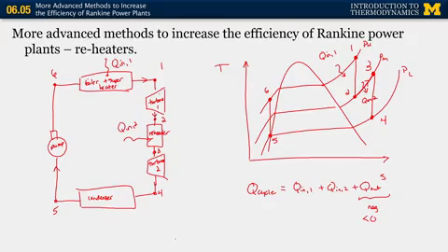Now, I drew this as a system that occurs in series so that we could see it very, very clearly. In reality, there aren't 2 turbines. There are staged turbines. So this would actually be a 2-stage turbine where we're withdrawing some fluid to go through the reheater, and then it expands through the second stage of the turbine. Okay, so again, this is drawn for simplicity. In reality, there aren't these distinct components. They're very much more compact.